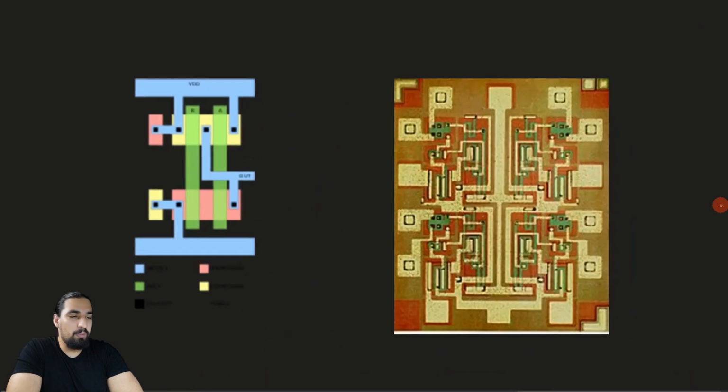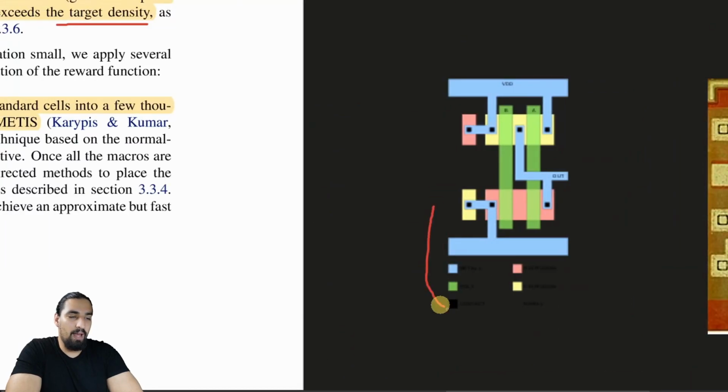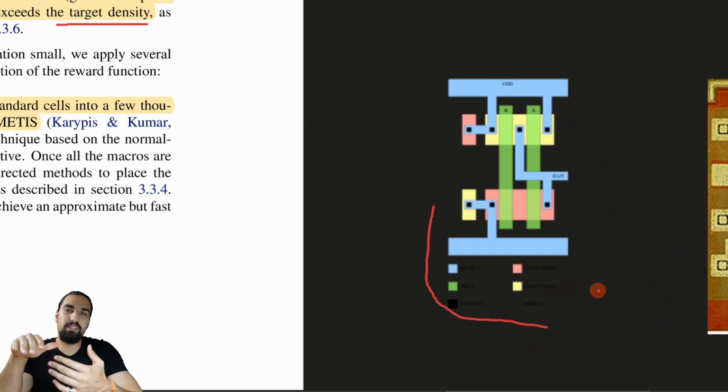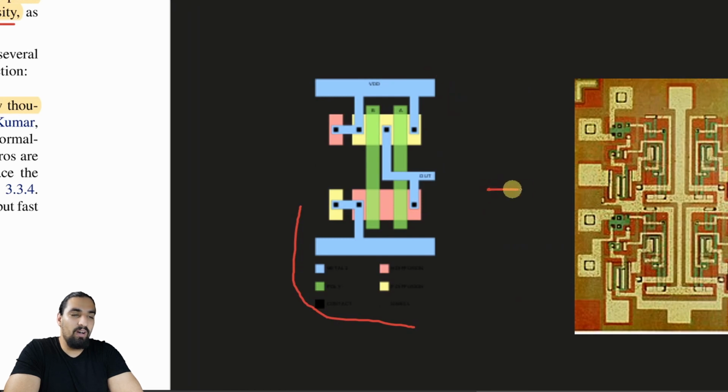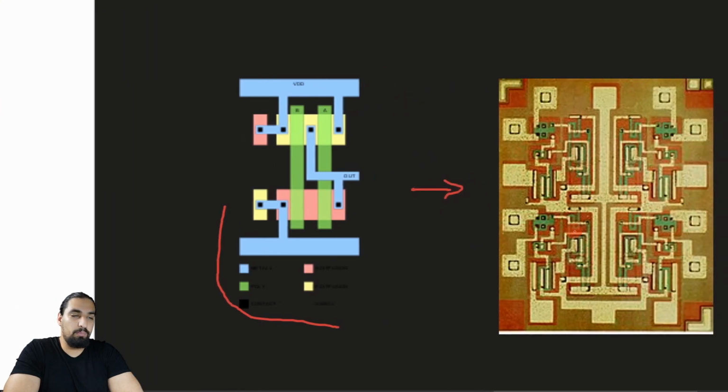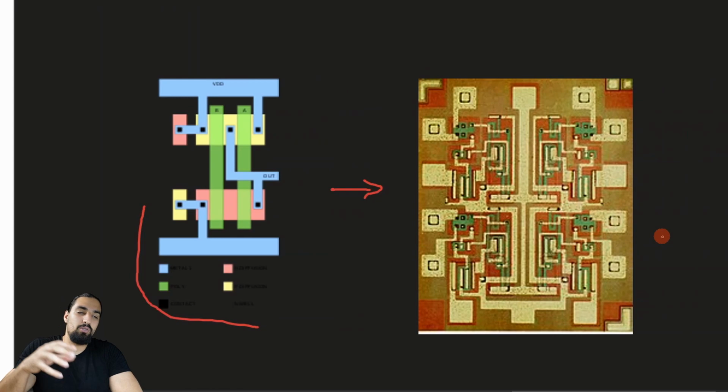And going even deeper, people have to design these, and you can see here, this is how you basically place these metal wires, and this is how you implement an AND gate. And finally you have the last step, and that's the production. You actually do some photolithography using light waves. You engrave these into silicon, and this is how multiple NAND gates look when actually manufactured.